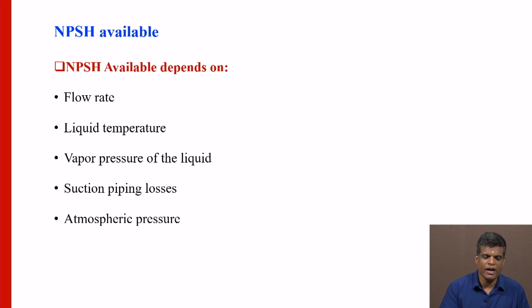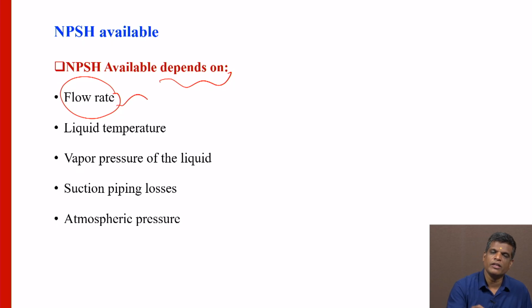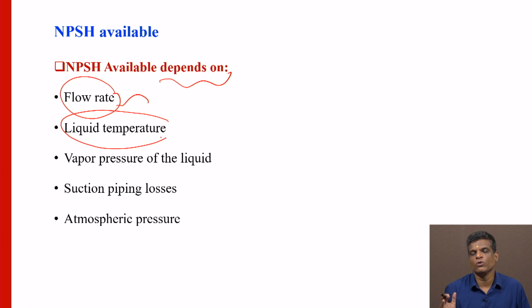So, net positive suction head available mainly depends on the flow rate of the system, whether the flow rate is high, low or medium. Then the liquid temperature is another very important factor. Then the vapor pressure of the liquid, Vp or PV.